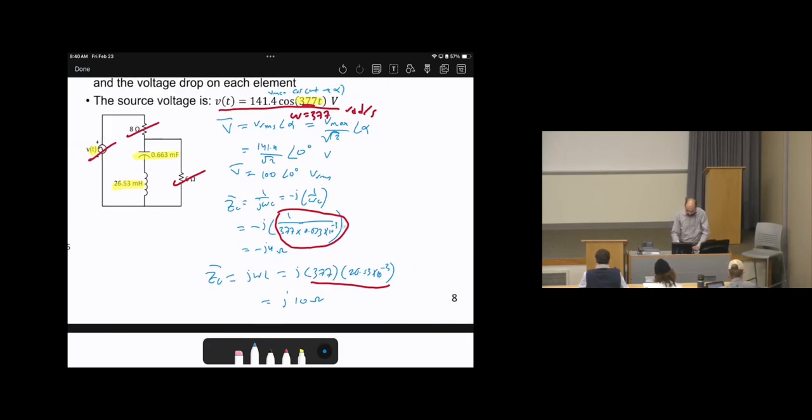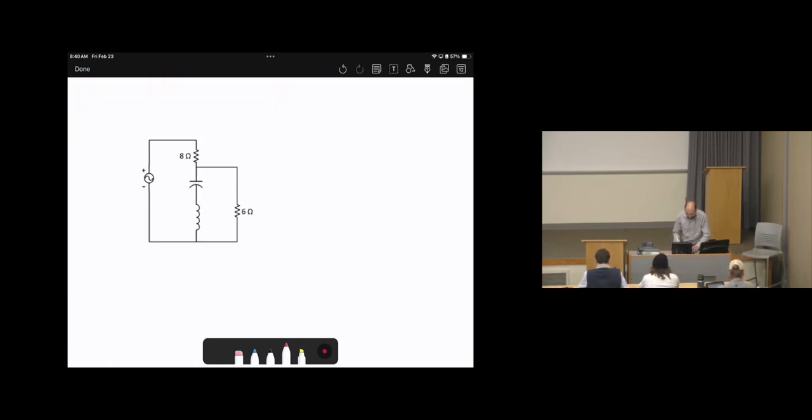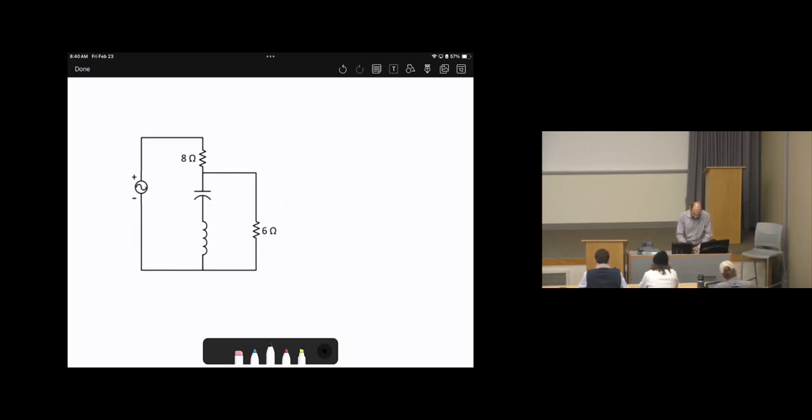Now, we did convert the capacitor and the inductor. That's great. The next step is to redraw the circuit and put all of them in ohms, the ohmic value. So we're going to redraw the circuit and put the new values in the phasor domain. This is 100, angle 0 degrees. This, we calculated as negative j4 ohms. This is j10 ohms. Now everything is in ohms, right? That's great. Then again, reread the question and see what we need to find.